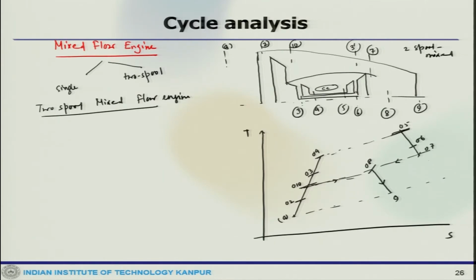One requirement for the analysis of the mixing process is equal static pressures and also equal velocities. So, from the layout, two conditions are specified. One is P3 prime is P7, and another is the velocity V3 is V7. This means there is no pressure loss in the bypass duct connecting the cold and hot stream, and no pressure loss in the mixing process.